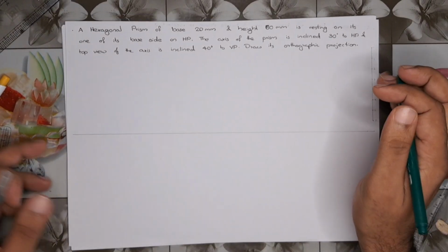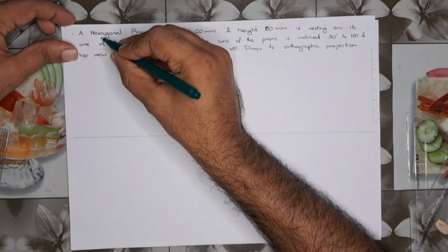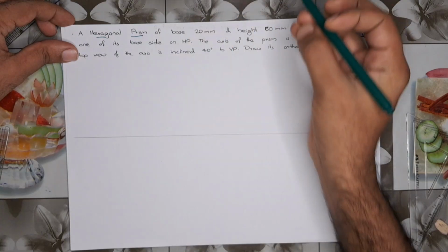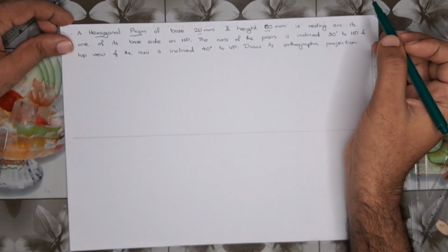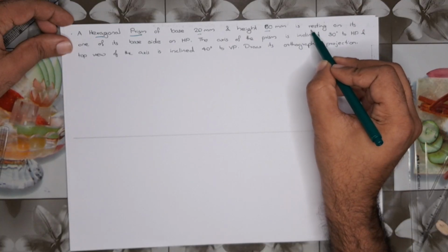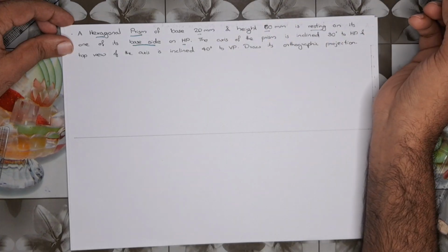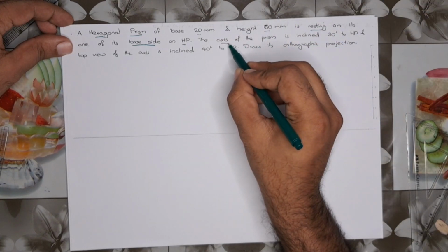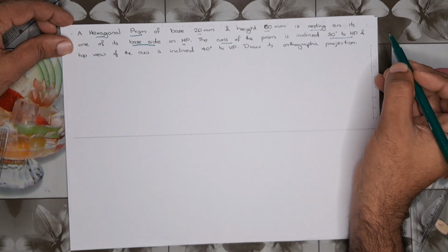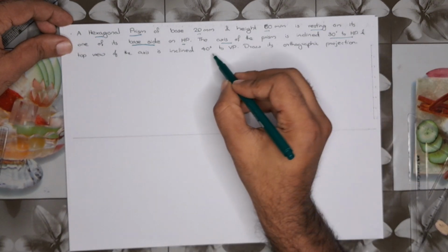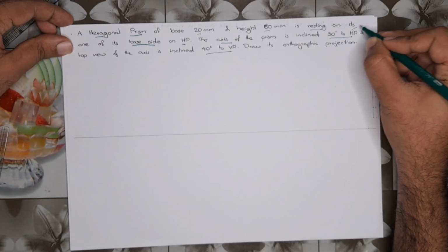Good morning all. Today we are going to discuss the double inclination of a hexagonal prism of base side 20 mm and height 60 mm. The important part is it is resting on one of its base edges on HP, and we can see that the axis of the prism is inclined 30 degrees to HP, and the top view of the axis is inclined 40 degrees to VP. So this is the first inclination,